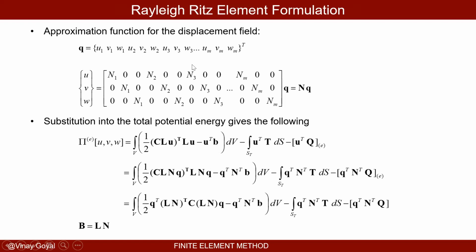And the shape functions are selected in a smart way so they satisfy the partition of unity property and the Kronecker delta property. So with that said, this whole thing is in bold. This bold U is this whole thing. And I'm ready now to substitute this into the potential energy. Looking at a single element, the total potential energy is this whole thing minus this minus that.